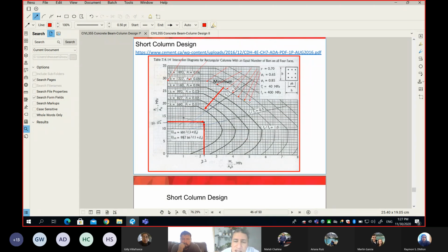The ratio between the stress in the steel and F yield is anywhere between 0 and 0.5. How about from these points here? Here the stress in the steel, Fs, is equal to F yield, because this works like a beam with mainly moment without any axial force.